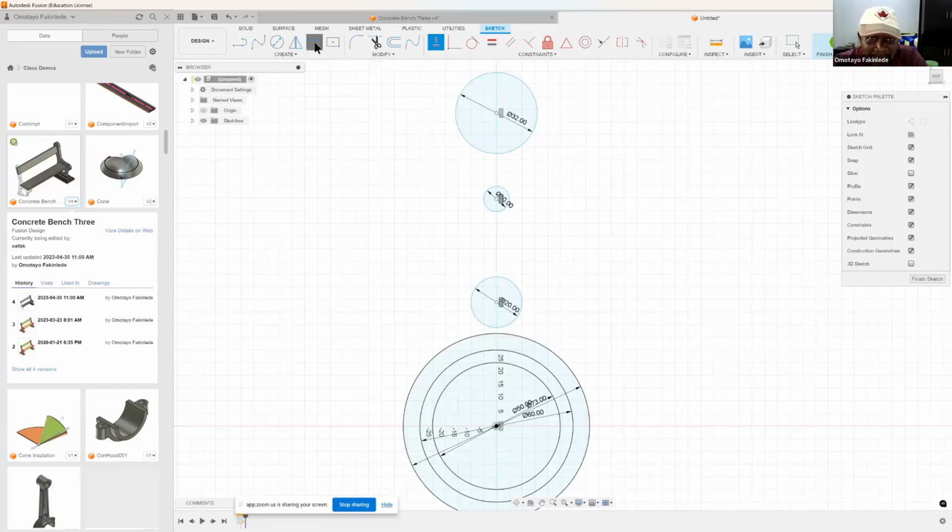So if I take the dimensioning tool, and I now say from this center to this center, I want it to be 50 units. I put 50 there. You can see now that immediately this circle is now black because everything about it is known. It's no longer mutable. The next one is 100 from the second line. So the dimensioning tool is still active.